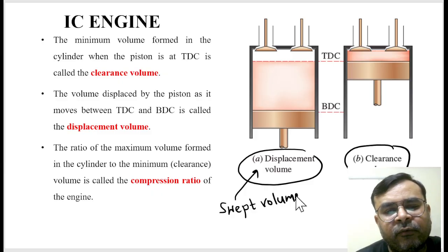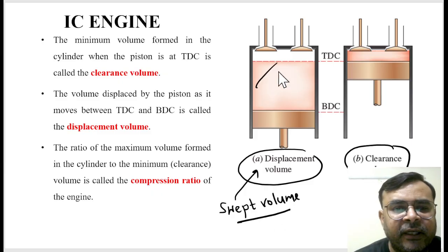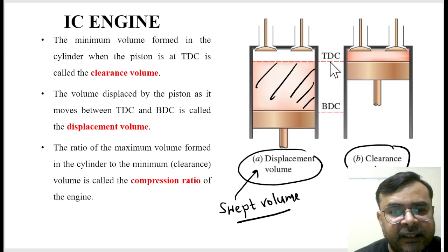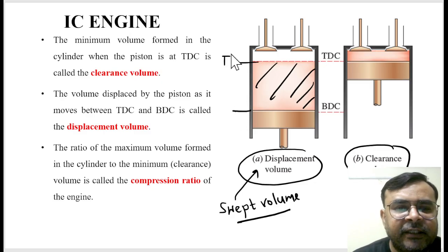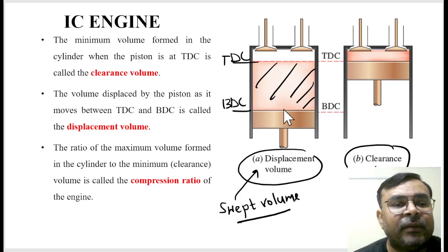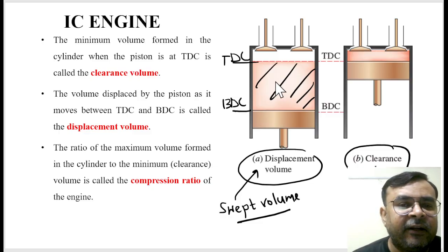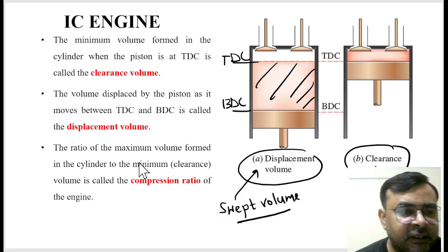So what is swept volume? This is the volume between top dead center and bottom dead center. Is it right? So you can say this is TDC and this is BDC. So the volume between the top dead center and the bottom dead center is called swept volume, or you can say displacement volume. Is it right? And actually this displacement volume produces the work input.